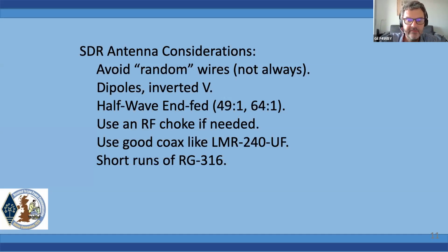And of course, lastly, and here I'm talking mostly about portable operations, we are dealing with low power, and it's important to use a good coax. I use LMR 240 UF. UF stands for ultra flex, but I think instead of having the regular LMR and the ultra flex, they should have had the ultra stiff and the regular, because it's not that flexible.